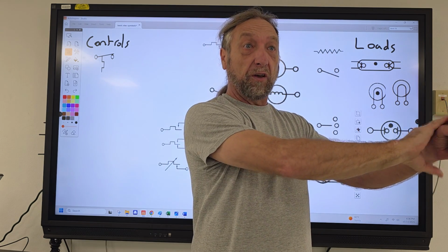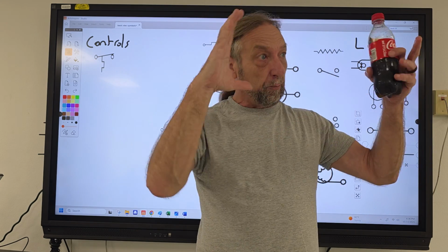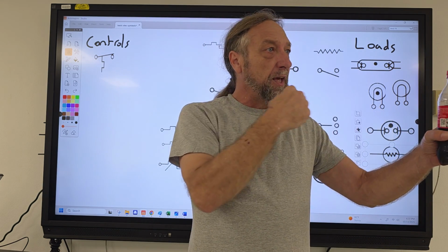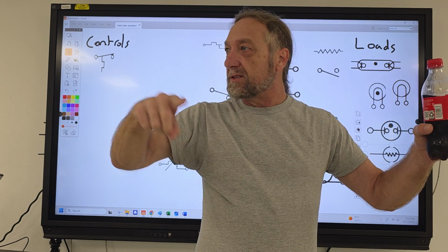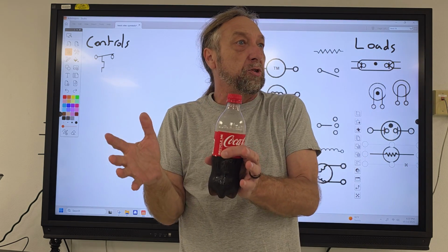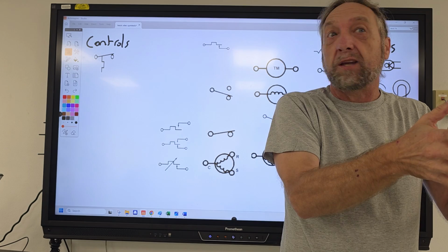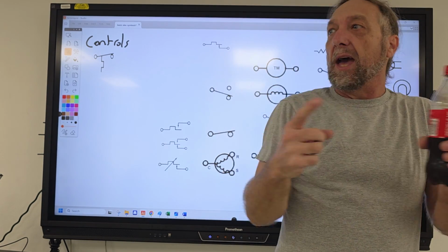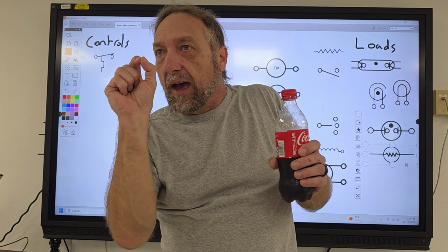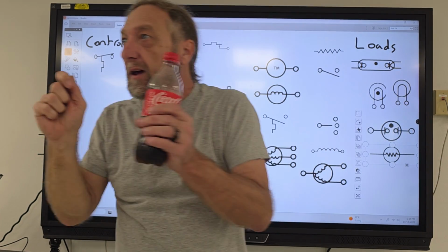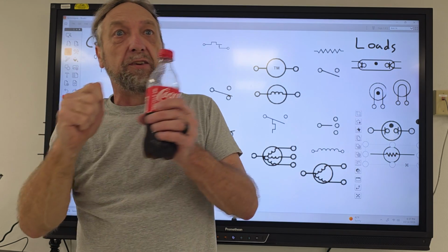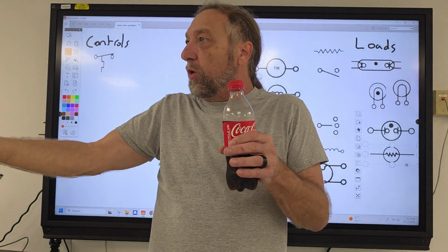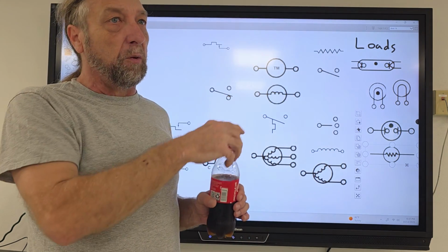So a thermistor is like your hand, and a computer board is your brain. The brain is watching this sensor, and the value of that sensor changes based on temperature. It may be 50 ohms at one time, and as it gets hotter, the resistance starts going up, and the board watches that and says, hey, at 50 ohms, it's 100 degrees, but at 150 ohms, it's now 1,000 degrees or something like that. And that's how the control board knows what's going on inside these appliances.